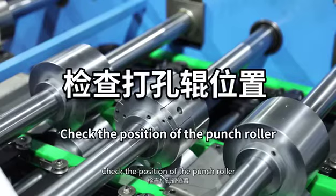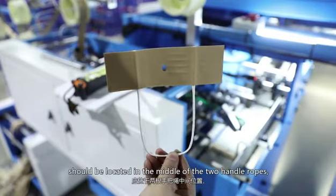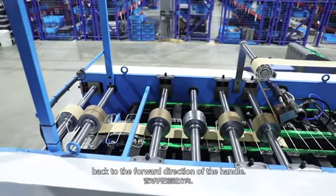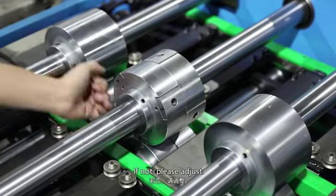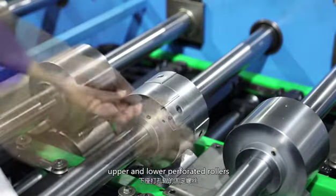Check the position of the punch roller. The handle positioning hole should be located in the middle of the two hand ropes, and the opening position of the positioning hole is back to the forward direction of the handle. If not, please adjust. Loosen the fixing screws of the upper and lower perforated roller.